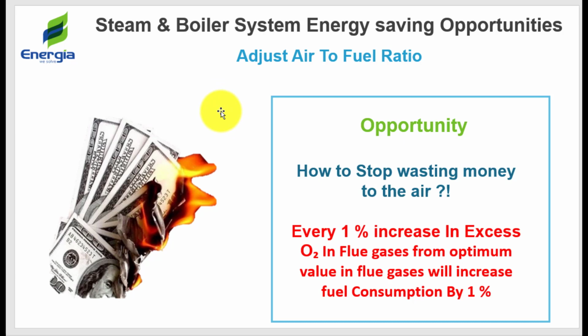increase in excess oxygen in the flue gas from the optimum value, this will lead to a 1% increase in your fuel consumption. And by the way, this is a very huge amount of money and value. Not only 1%; maybe someone will think it is something insignificant, but actually it is significant. This is why we will see in numbers this can lead to thousands and thousands of dollars of saving and